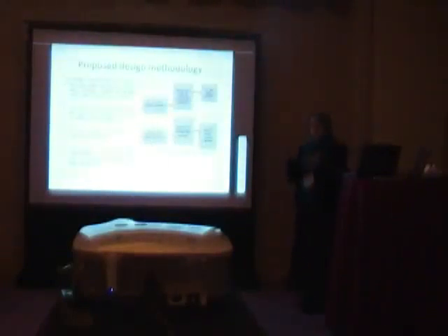Then we make some statistical analysis and we get the random and systematic components of the delay, so we get statistical delay. We use this in the design. How? Our design methodology depends on this: I have a floor plan for the NoC describing the XY position, height, and length information of each link. I have process variability parameters mentioning the mean and standard deviation for threshold voltage, gate length, and oxide thickness from the ITRS report.